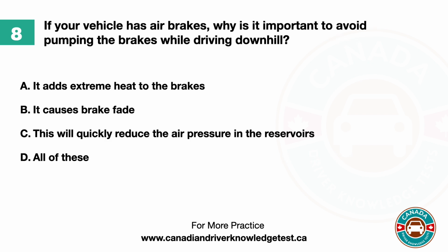Question 8. If your vehicle has air brakes, why is it important to avoid pumping the brakes while driving downhill? A. It adds extreme heat to the brakes. B. It causes brake fade. C. This will quickly reduce the air pressure in the reservoirs. D. All of these. The answer is C. This will quickly reduce the air pressure in the reservoirs.